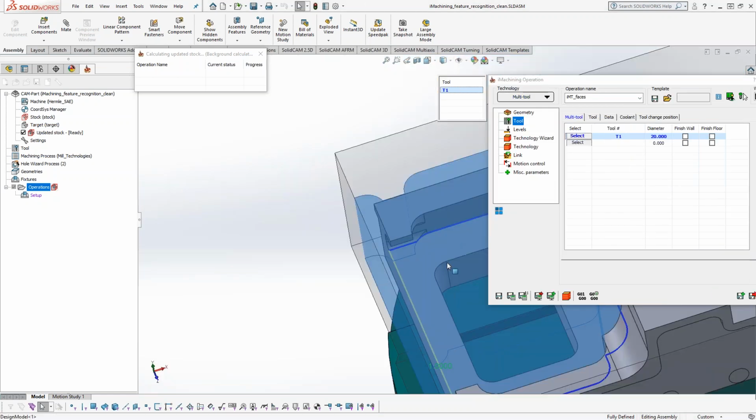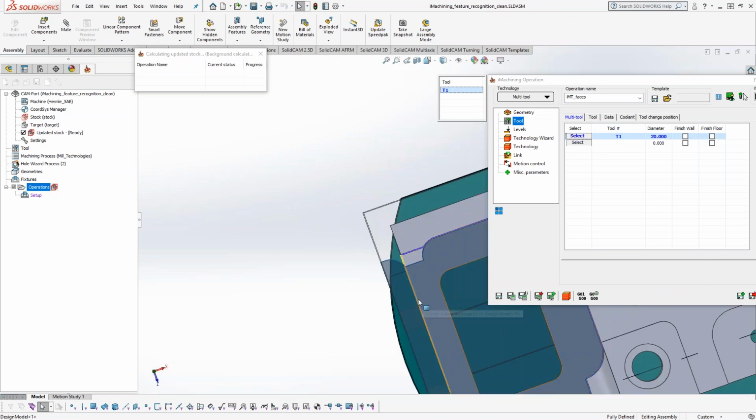And then the other thing we do is we then extend the region to the stock, because as we know, iMachining is all about smart cutting at the CNC. With the smart cutting at the CNC, we measure every engagement angle for every single point of the toolpath. The tool never plunges on material. All the lead-ins and lead-outs are done in air. All the repositioning is done in air. So when we did the feature recognition for iMachining, it's important that we took into account the stock automatically.